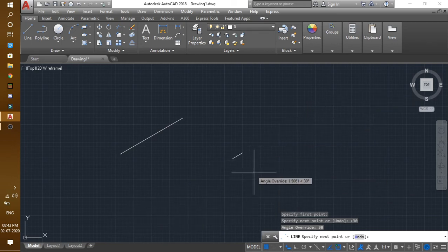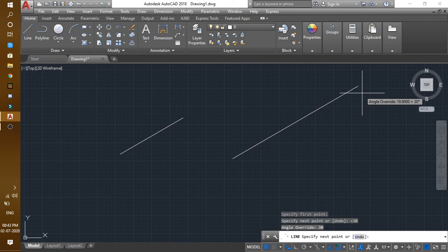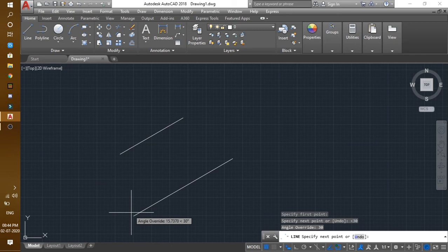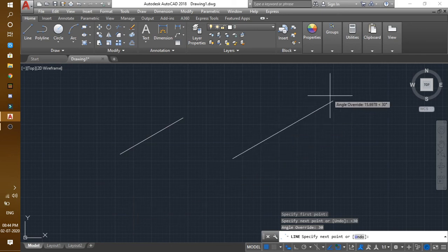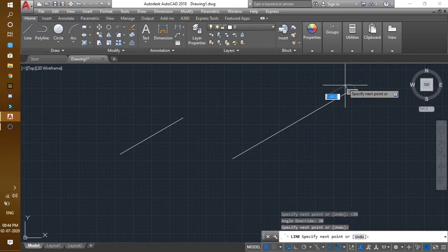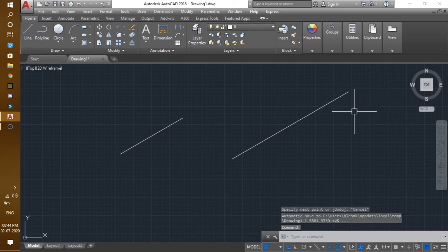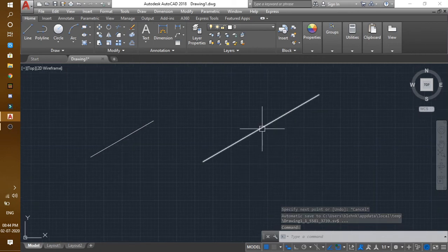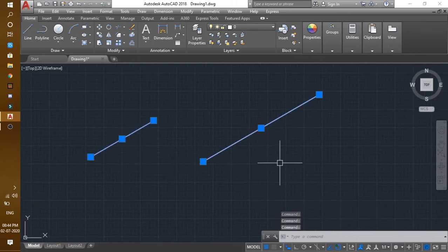Now this is useful in scenarios in which you don't want to enter your length, that is, you want to draw a free diagram, I guess. So your line will just be locked to an angle, and after that you can choose how far you want the line to go and just click the left mouse button like that, and here is your line with an angle of 30 degrees.